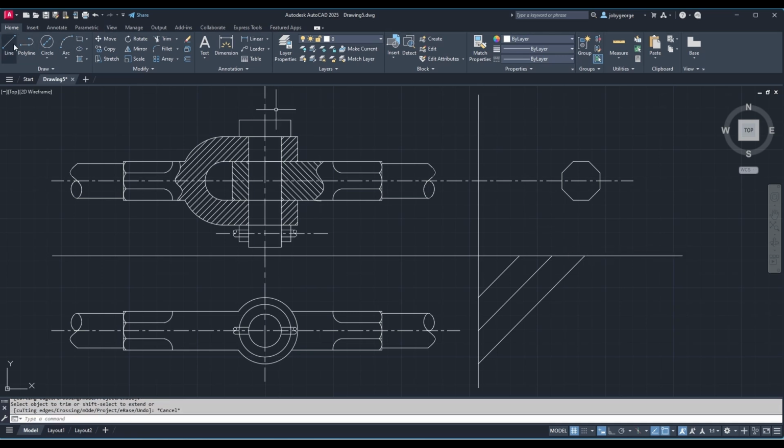So this is basically my center line, which will come on the side view like this. And I'll change the property to center line by clicking on that. I have come into by layer and change the center. I will move the center of the polygon to the original center by clicking on that and moving the polygon to the center.